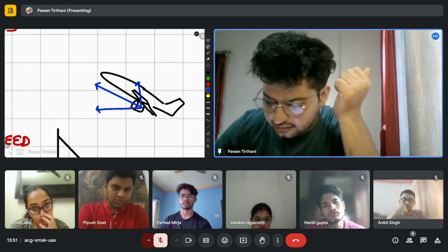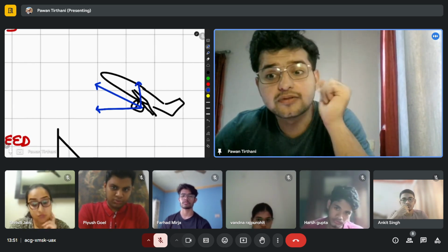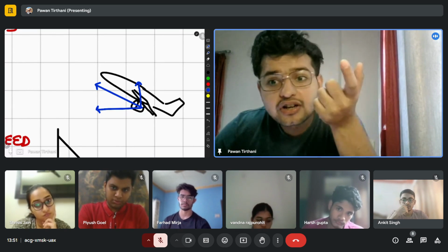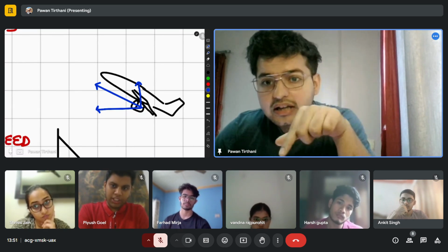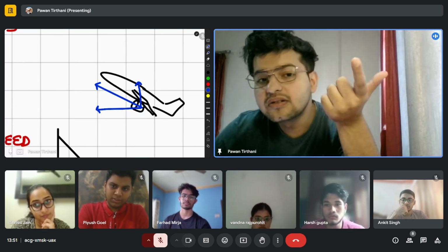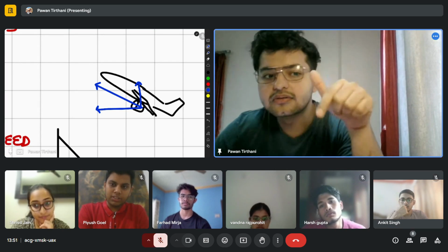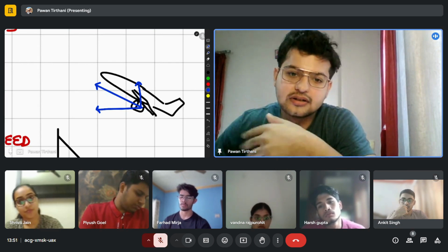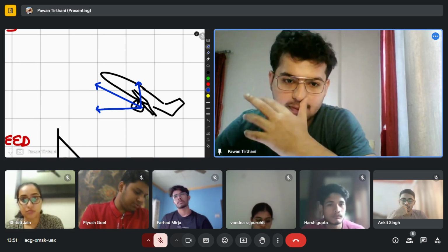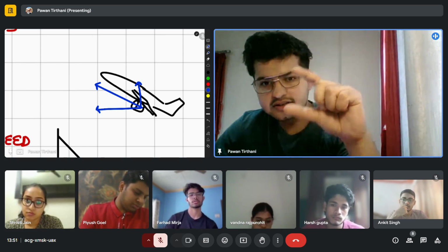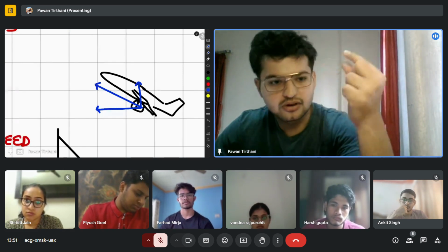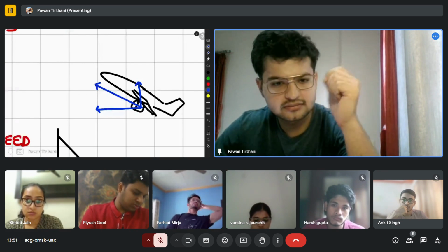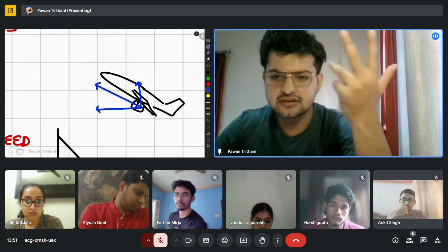This component of thrust is supporting the weight of the aircraft. So lift required to produce is less. Stall speed is lower. So basically, instead of lift supporting a component of the weight, the thrust is supporting a component of the weight. It's marginal. It's a very small value. It's a very small factor, but it's something that manufacturers and everyone, they think about.